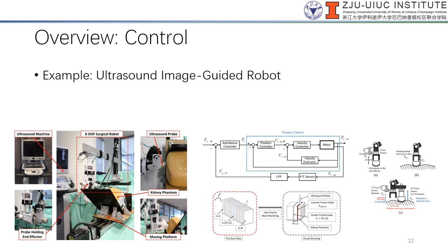In this case, the robot can actually stabilize the movement of the patient. Because the patient will be breathing, the patient will be moving, and it's very hard for the surgeon to send the needle to the right position by looking at the ultrasound and multitasking a lot of different things. They have to position the probe, look at the ultrasound image, and look at how the patient moves and breathes, and insert the needle accordingly. Sometimes the needle will bend and things like that. So the robot turns out to be a very good candidate in executing precisely what is planned, but responding to the environment requires some form of perception that comes from your ultrasound image.